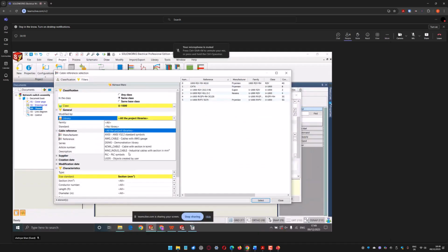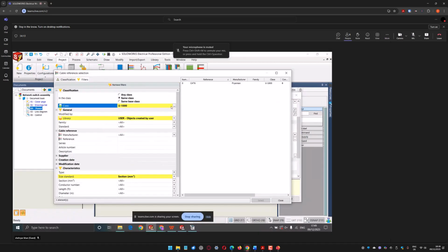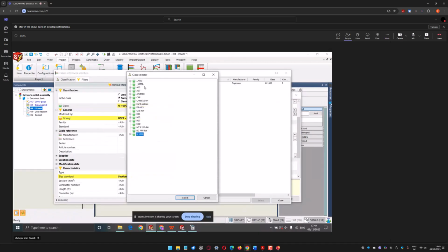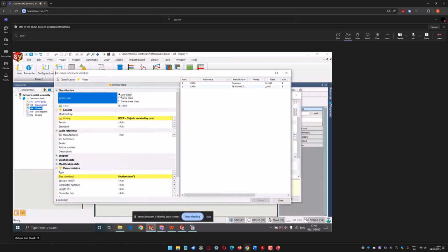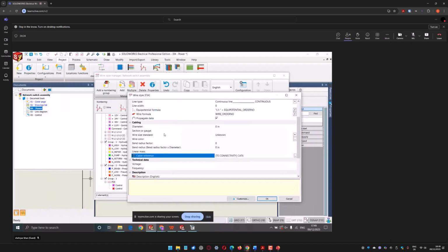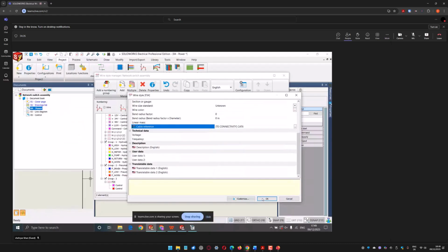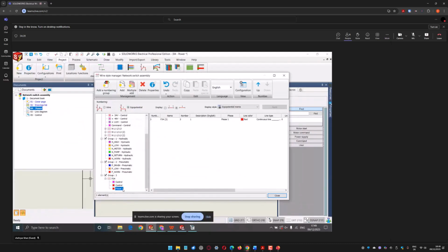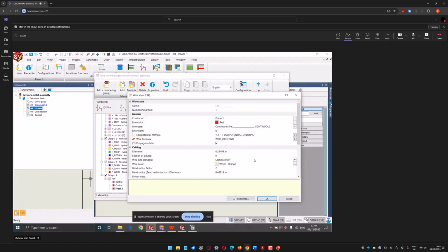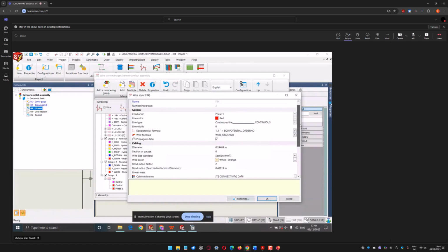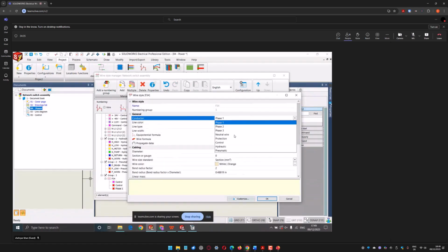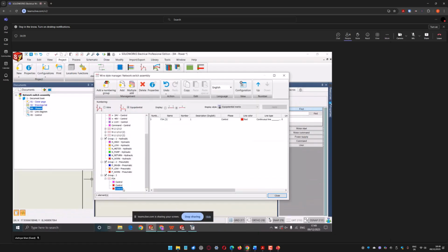We can come here and then choose from our user objects class. Let's keep it the same, any class. Yeah, the TE connector, the TE cable, sorry. And we use it as a connection and press OK. Here again, I'll change its properties. I'll make it control instead of phase. And then we keep doing this for like 8 wires.